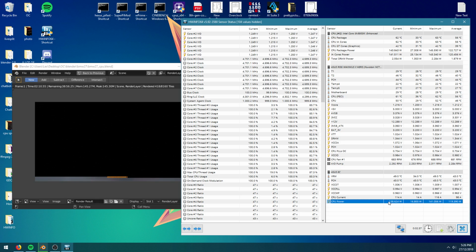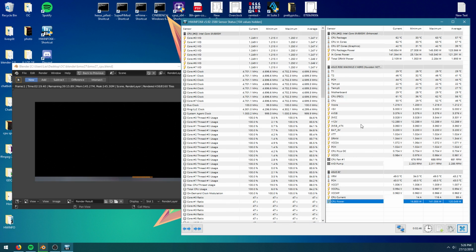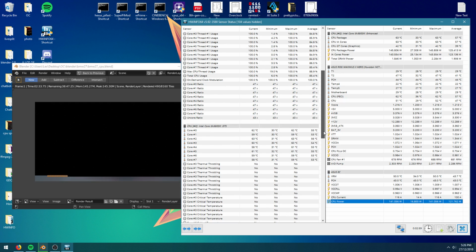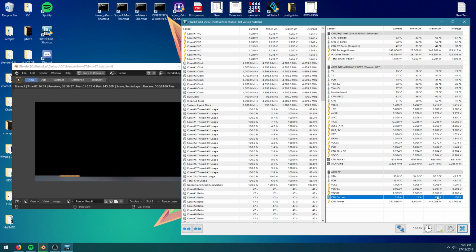So the thing is, if it's only pulling like 90 watts or maybe even 140, it's a bit deceptive right now, but if it's not pulling enough power for the stress test, it could be because you're limited by amps. In the BIOS, there should be a current limit, and you need to pretty much raise that to as high as it will go, which is pretty much 255.75, but 250 amps, and you can see I'm not pulling anywhere near 250 amps. The default is much lower.